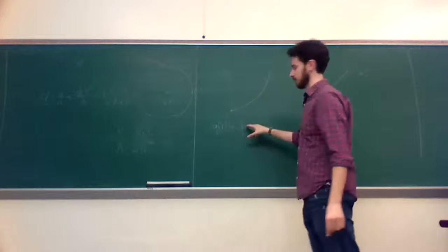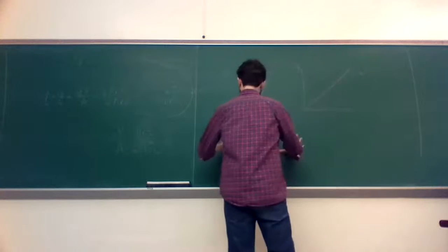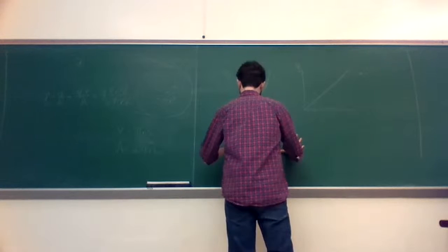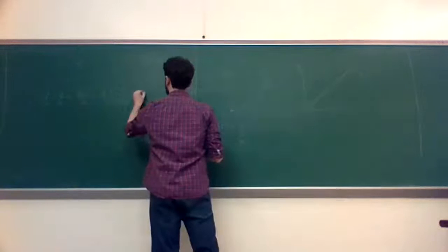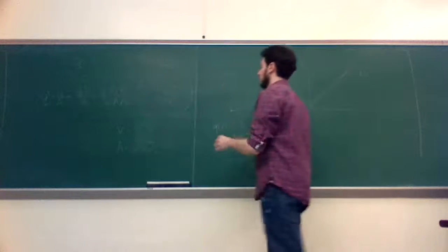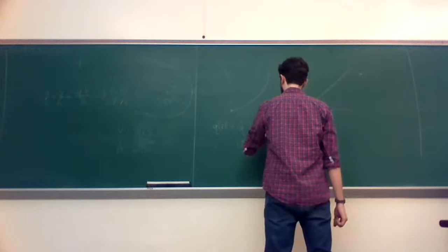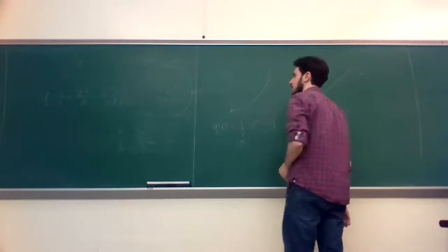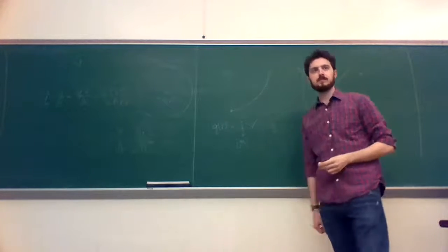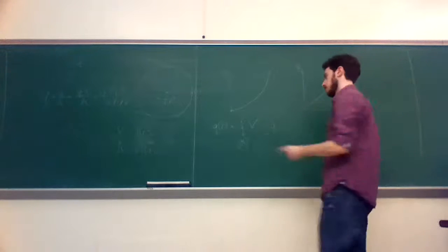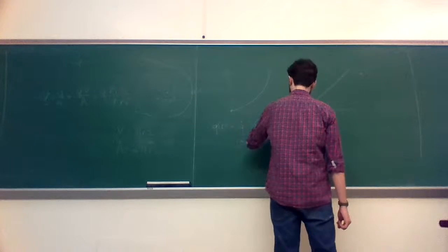I think that's what we're using for Q gen, which is in watts per meters cubed, times the cylindrical control volume. So what is that? Q dot times, what's the volume of an arbitrary cylinder? Pi r squared L. Pi r squared L, that's our number there.